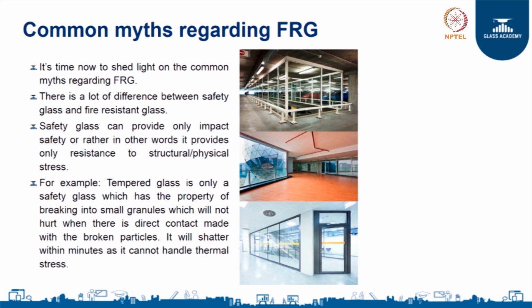So, it is not advised to use a product which is made to withstand impact loads, or has a high thermal stress coefficient, as a fire resistant glass. Actually, safety glass can only provide impact safety, or in other words, it only provides resistance to structural or physical stress. So, it does not mean that we can use any type of safety glass as a fire resistant glass.